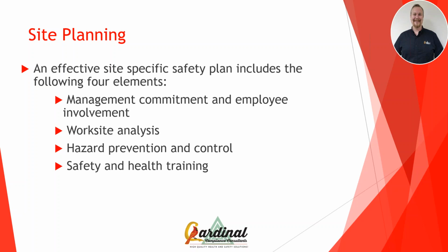It is very easy when you take a journeyman, let's say a journeyman Boilermaker, who has worked in construction all his life, has 10, 15, 20 years experience, and you go to start asking them questions, let's say about an anchorage point. The reason you're asking him about this is because you noticed, wait a minute, his anchorage point is a 1-inch electrical conduit and it's live. Now, again, if you've worked with fall protection, you already know what's wrong with that statement.